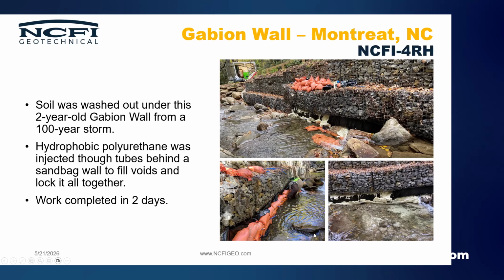We also had a boom downstream to catch anything that did escape past the sandbags and get out. By the time it gets past the sandbags, it's solid foam. We use the 4RH, which is a 4-pound density, compressive strength, pre-rise about 80 psi. So you can see there was already a bow in the wall, and that's not because we threw all those sandbags there. It was already there.